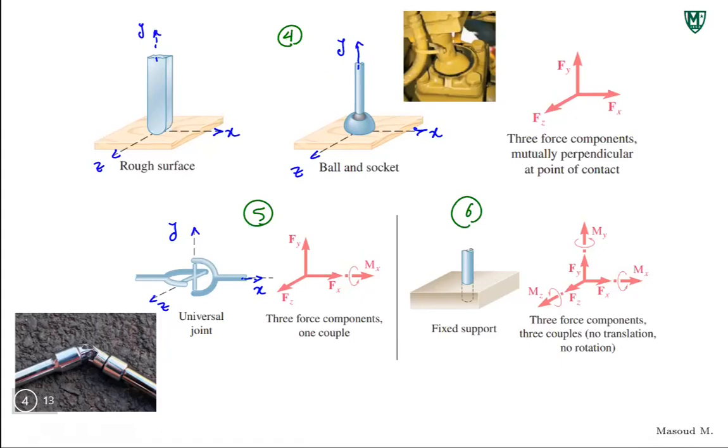So the only type of rotation it prevents is rotation about this X-axis. And that's where you're transferring your force. Right? You're turning the shaft using the engine, and it's transferred into the wheels in the back. So when you have this type of joint, when you remove the joint, you have to consider 3 forces and 1 moment. So 4 unknowns.